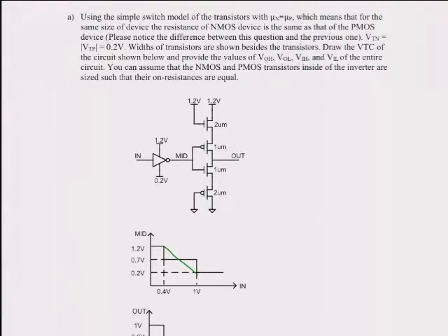Right? Now, this is just saying, if you take the switch characteristic to the extreme, you said the transistor turns on, you have the on resistance, and the on resistance doesn't vary. Then you fall right away to the VM. And you stay at VM till the other transistor goes off, and you get this kind of staircase characteristic. But the staircase made life a little bit easier for the next steps.